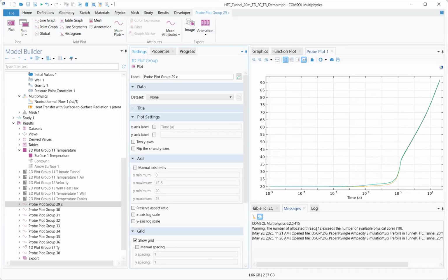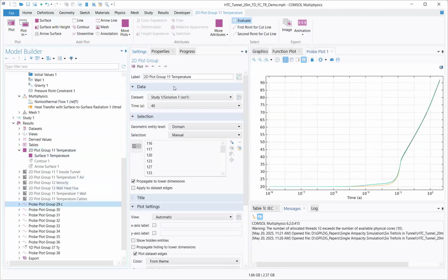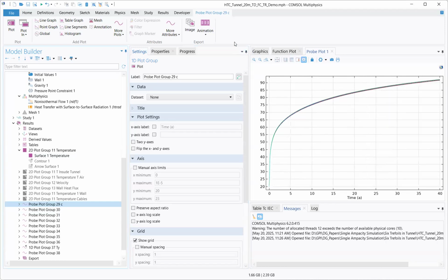Go back to the previous figure, please. It's something important I need to explain here. The temperature rise, the exponential saturation. This one? Yes, that one. As you see here, the temperature is rising, but very slowly, because this is deep. How deep is this tunnel? 20 meters, I believe. 20 meters deep. So the time constant takes 40 years, not even. It takes 200 years to get to steady state.